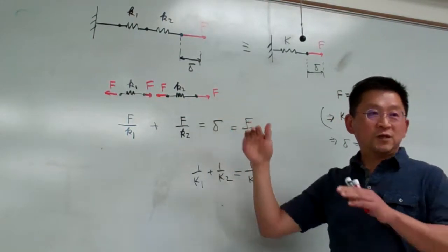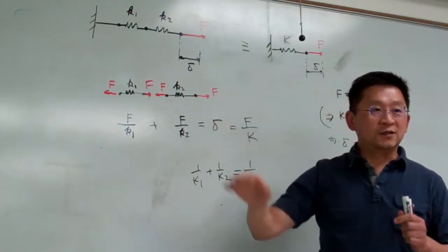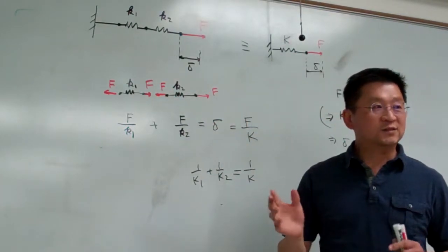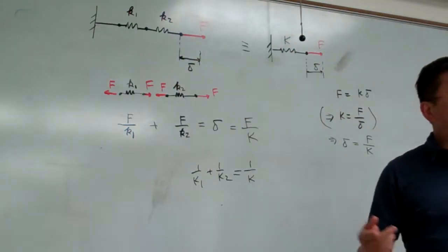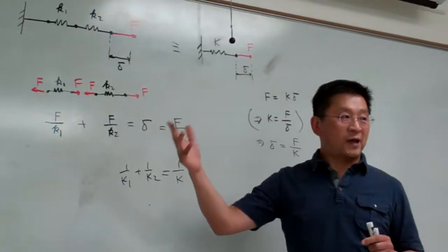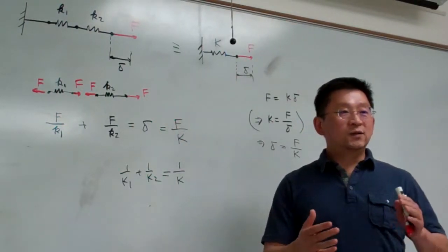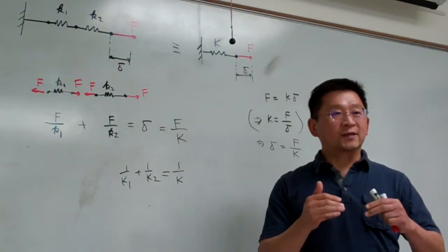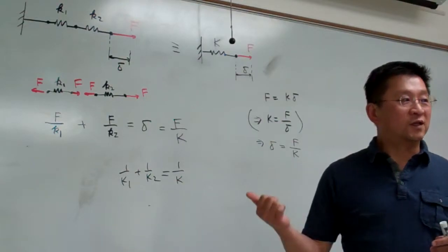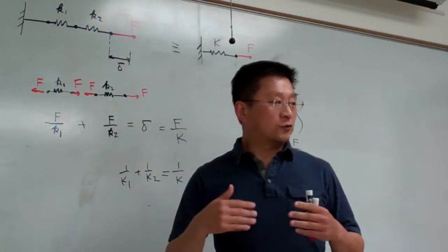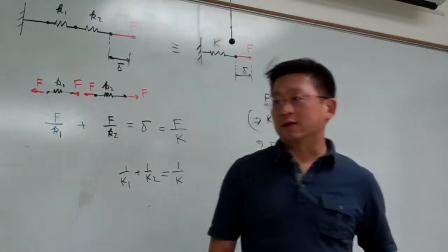The force is simply transmitted through the spring system. And here I emphasize that many times the connection of the springs will be a mixing of parallel and series connections. So at that moment we do need such techniques to do the calculation level by level. Okay, and we'll see.